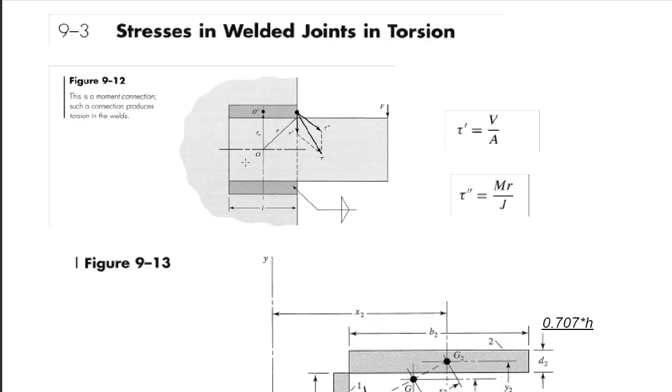To that wall we're going to weld a plate. Both of them are almost in the same plane, but rather than drilling holes into material and putting bolts through there to represent the direct force and the moment created by this direct force, and calculating primary and secondary shear stresses for bolts, we're instead going to do the same thing for welds.